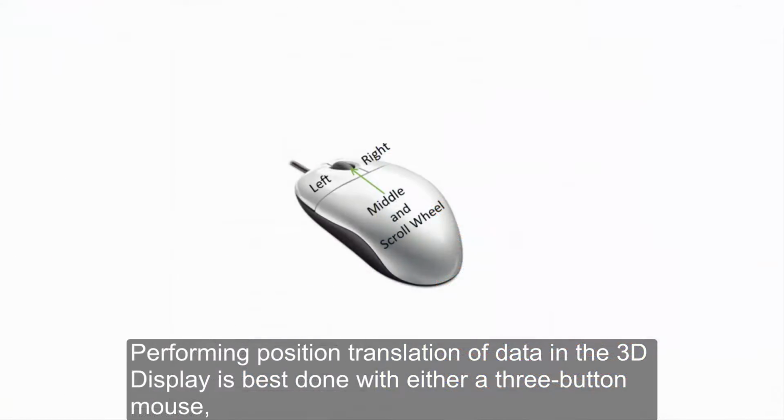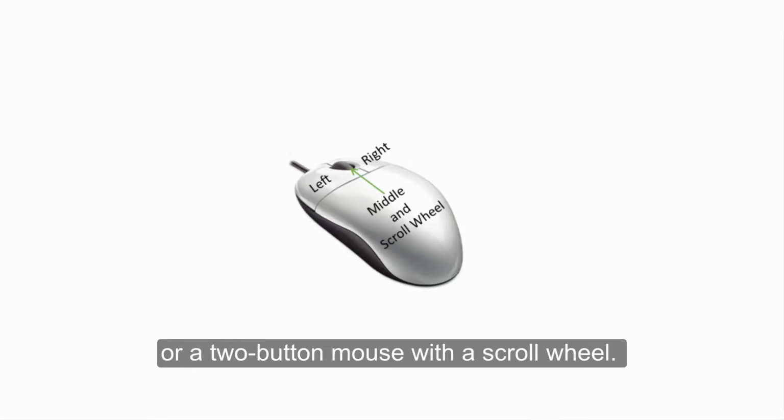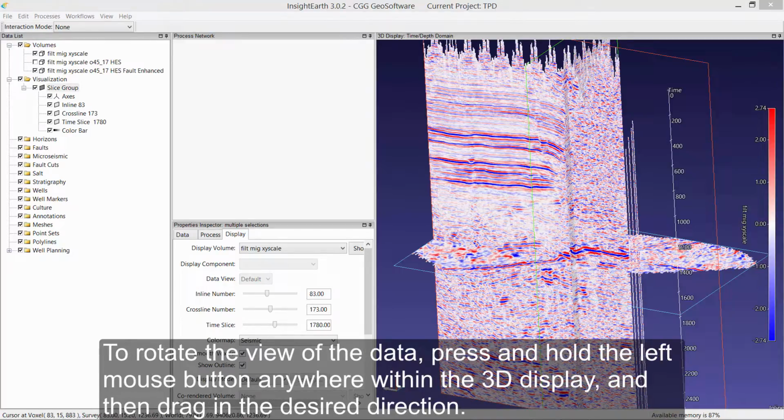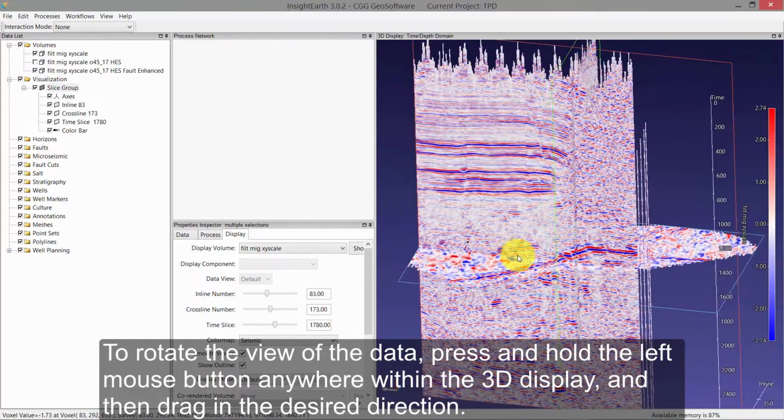Performing position translation of data in the 3D display is best done with either a 3-button mouse or a 2-button mouse with a scroll wheel. Most operations are performed with either the left mouse button or a combination of the left mouse button and the Shift or Control keys. To rotate the view of the data, press and hold the left mouse button anywhere within the 3D display and then drag in the desired direction.